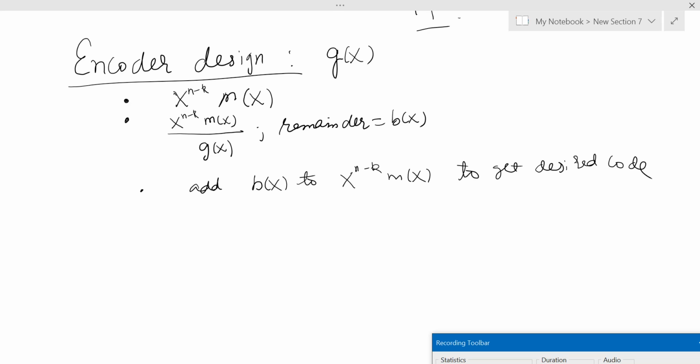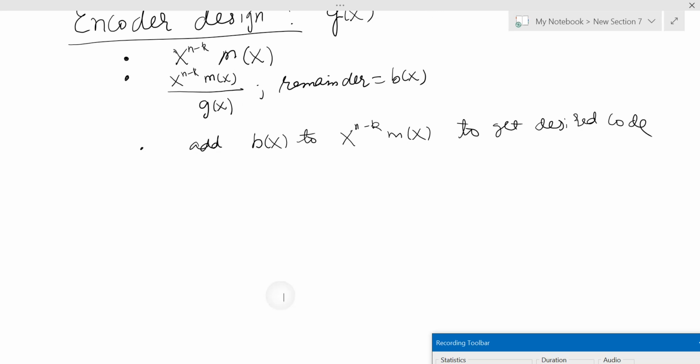Okay, see what is done. Each degree, as I told you, suppose you multiply x with something or x square with something, it actually means you are shifting, right? So you will use flip-flops as those shifting elements. And so what will be the rules? We have here a flip-flop. It simply stores a bit, and whenever the clock ticks in, whatever is at the input is stored, and whatever is inside the flip-flop comes out of the flip-flop. That is the simple rule of a flip-flop.